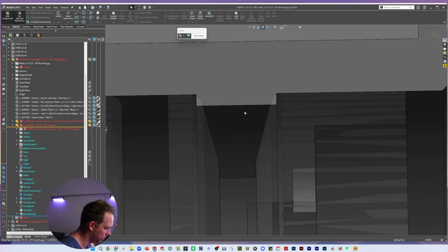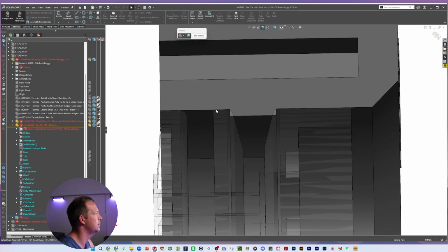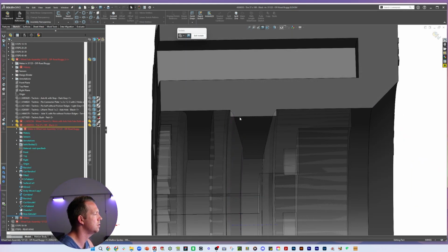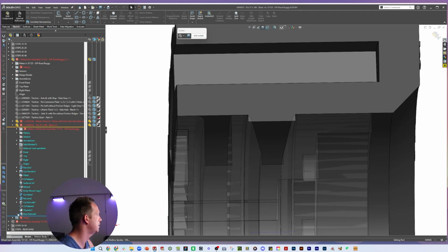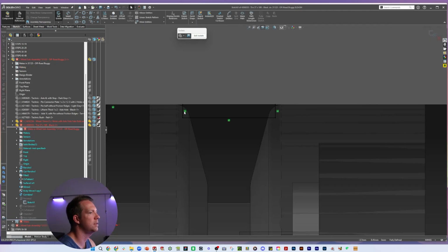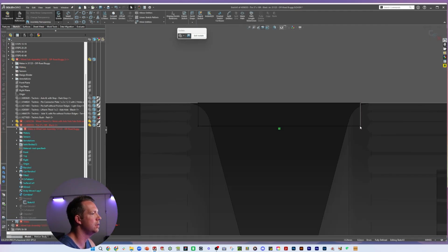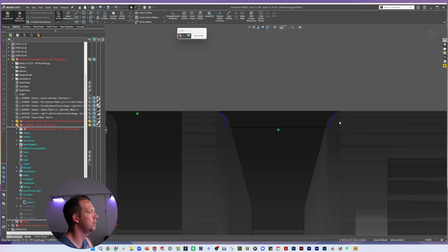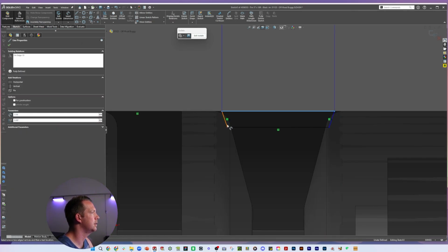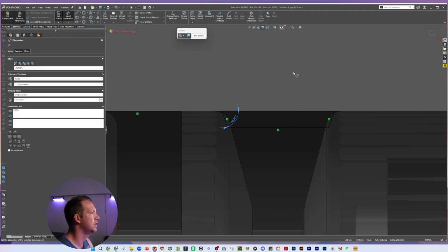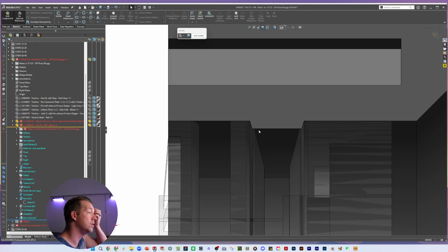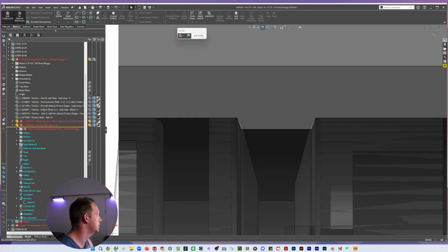Now, it is possible that those faces actually have a chamfered appearance. Okay, so why don't we try that? That's this section here. If I just delete that relation and that relation, I can tweak, give them an angle, I can make them equal, and I can set that angle. Let's say it's 70 degrees. Once again, we're getting a bit closer. We still have interference, but you can see how our dimensions actually weren't that far off.